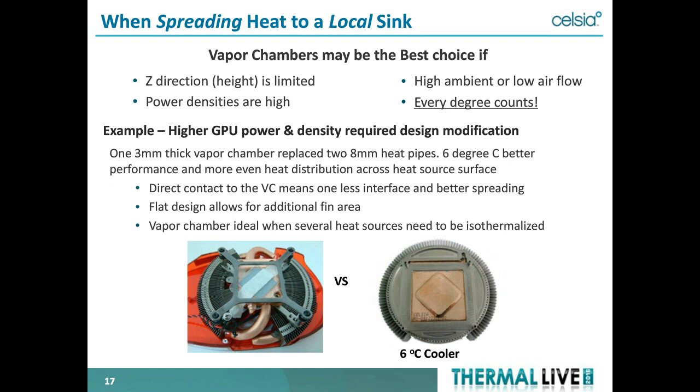Now, we will occasionally use vapor chambers for spreading on a local heatsink also, just like heat pipes. Vapor chambers really are the best choice if you really limit it in your space, your Z, generally that's your height, is limited, or your power densities are high, or your airflow is low, or it's just a challenging application where you need every degree you can get.